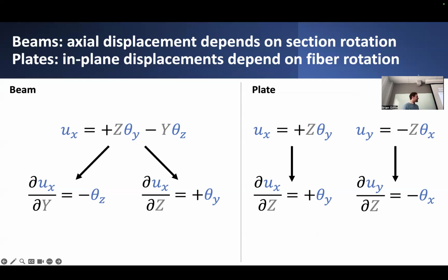its various components, with respect to various position coordinates of various points and how they varied with respect to those different coordinates. So we might want to look at things like, how does the ux component of displacement vary as a function of y? We can compute its partial derivative. And notice that it's basically just directly equal to theta z, again, assuming that it's a rigid rotation that's happening. Same thing, we can look at the partial derivative of ux with respect to z. And notice that it's related directly to this assumed constant rotation theta y.